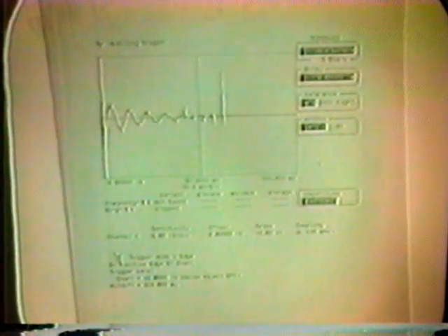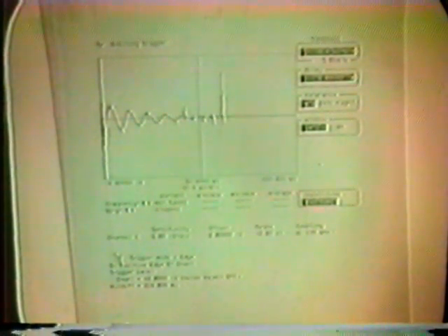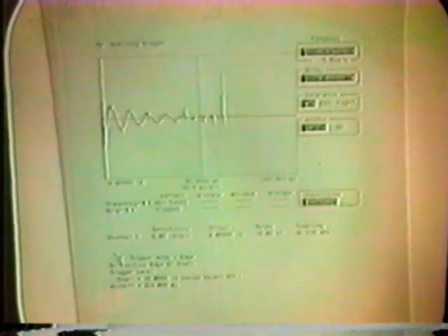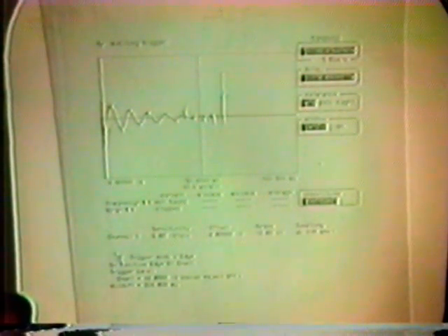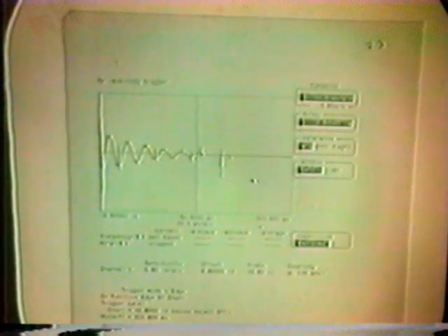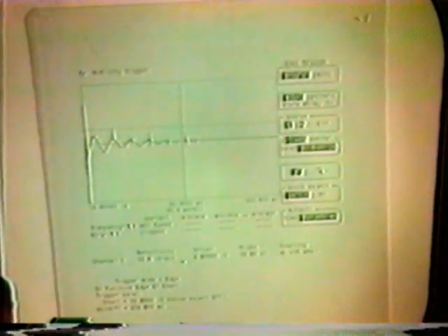No way you are going to see these spikes if you are using an old analog oscilloscope. The excursions here are too short to be visible on a screen. The only way to see those is using a very fast digital single shot oscilloscope, where every point has the same luminosity, independent of the duration of the trace. You might think that this is an artifact. Let's take another one. Still the ringing frequency is there, and the artifacts still present. Another one. And another one.